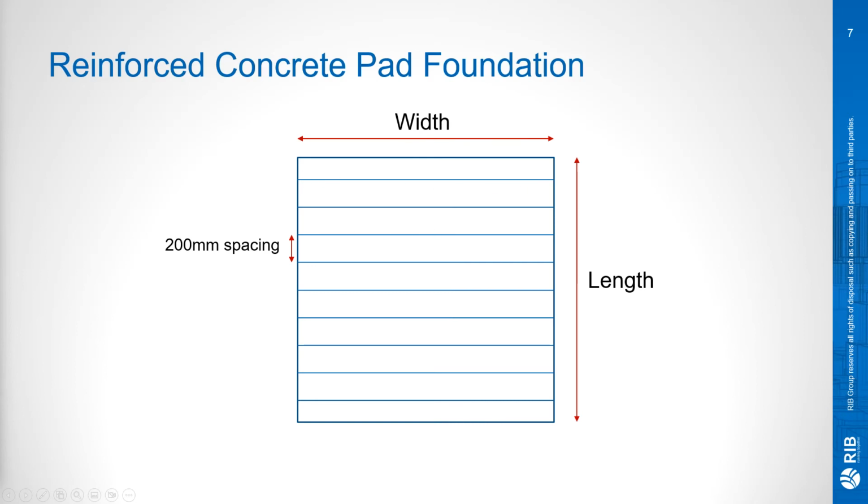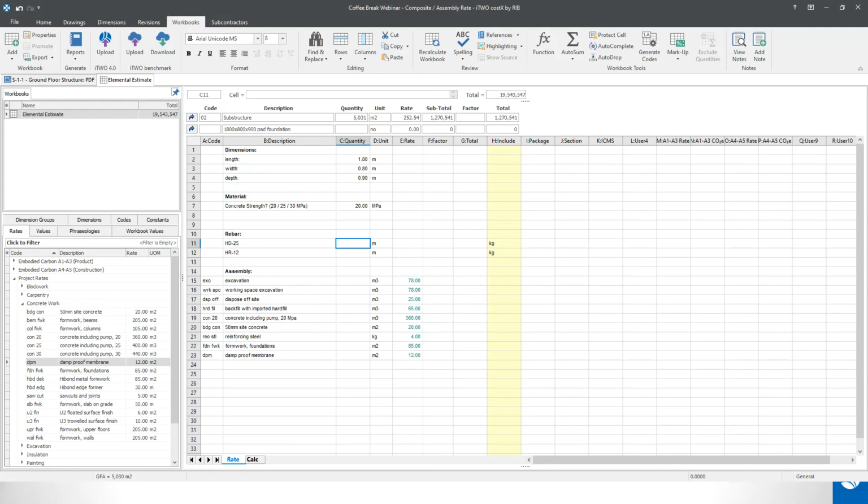So we'll switch over to costX again, and let's build that formula. Click into the formula field and start by typing in equals. Open a circular bracket. Now I'm going to use a function which is R1. What this function does is it will take the number of instances that you're calculating and add 1 at the end.